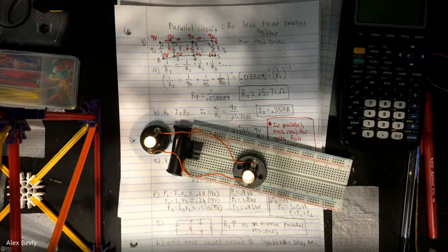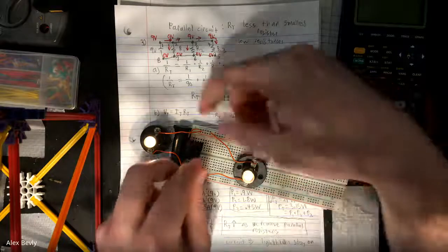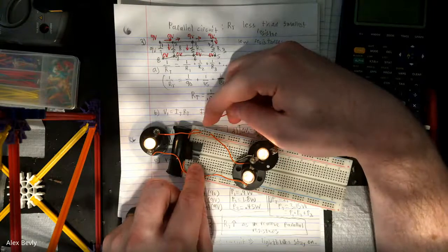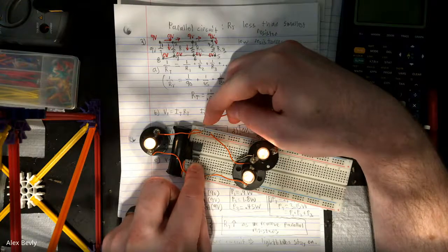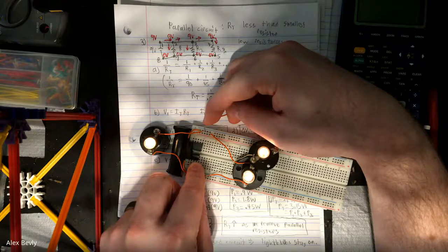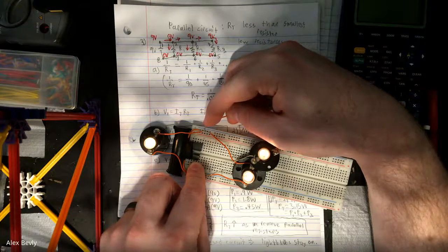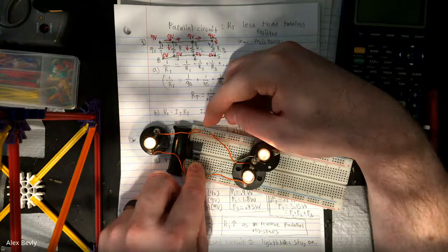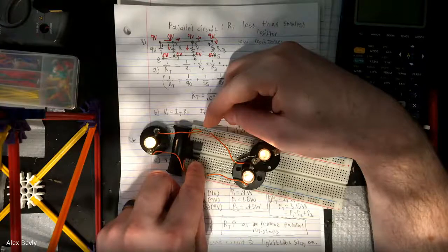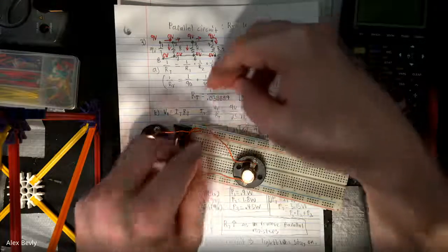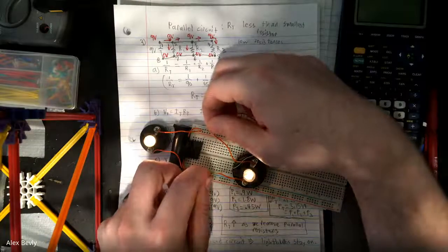So I plug two of these in, and they're still really bright. I could add a third one in, and they're all going to stay equally bright. So I keep adding these in parallel, and they're staying the same amount of brightness, right? This is a really nice thing about parallel. I can keep adding. What's happening is the total resistance of the circuit goes down as I keep adding things in parallel. As I get lower resistances, I get bigger currents. So all of these are having to share the current, but because the overall current goes up, they don't have to end up sharing more. So let's add more, or let's actually plug you in.